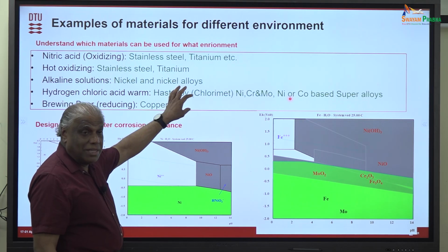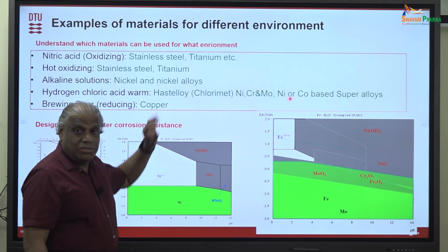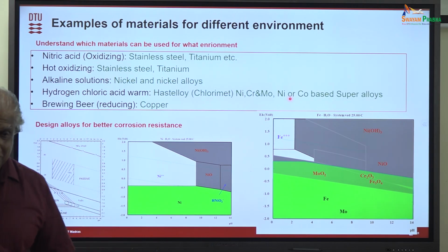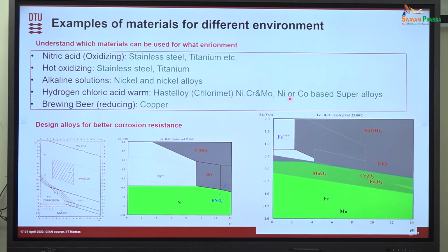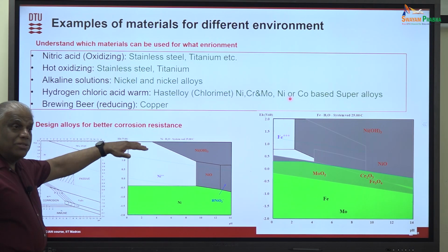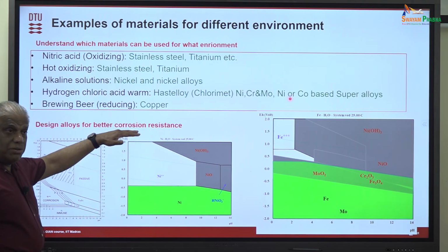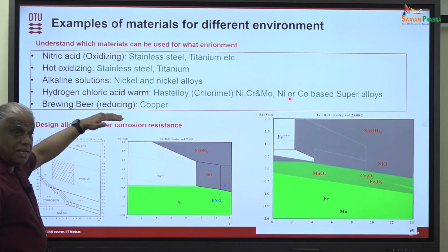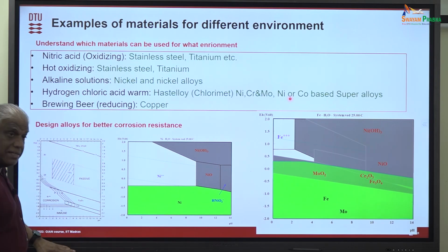This will cost more than gold. They have to make it with such material, because otherwise the flow loop itself will corrode while doing the corrosion testing. Similarly, for reducing conditions, normally we use noble metal. Because it's reducing, it's already noble metal. If you use passive metals in a reducing condition, you're automatically dropping, right? All the passive layer is removed.